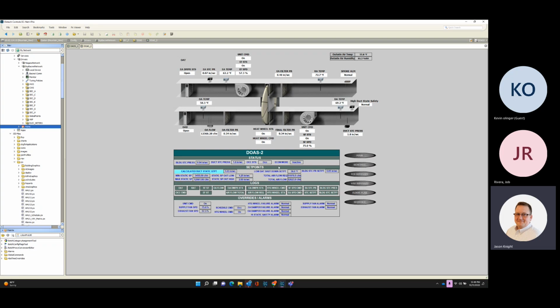And our max static set point we're trying to make is 2 inches. So since we're 1,900 underneath what our max is of 2 inches, it's calculated at 1.9 inches. So it constantly resets and adjusts itself based on the total required airflow. And then I put this point on here just so you can see what you're actually delivering out in the field. This is the totalized airflow of what all your VAV boxes are making.